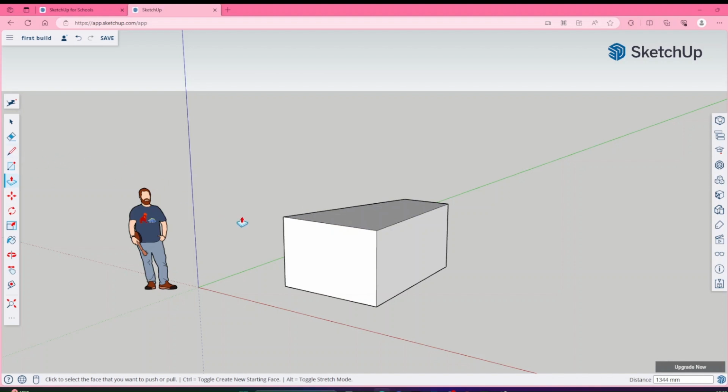So if I was to draw a line, I'm going to hit L again, and I'm going to draw a line on this edge. And I'm going to connect it here. And I have this shape that I can coplane, and I can remove material. Okay, so I'm going to go back on that. So I've connected, right? Because remember, this is one plane. I've got a line here, a little triangle. I can connect that. So I'm still coplaning that face.